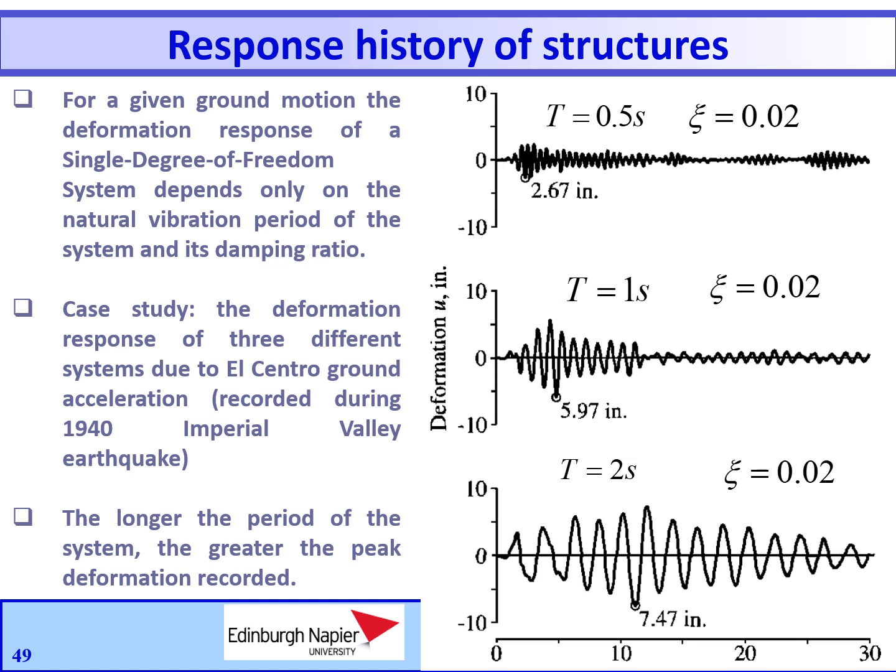It is seen that the time required for a single degree of freedom system to complete a cycle of vibration when subjected to this earthquake ground motion is very close to the natural period of the system. The peak deformation is also noted in each case. Observe that among these three systems, the longer the vibration period, the greater the peak deformation that is recorded. As will be seen in the following, this trend is neither perfect nor valid over the entire range of periods.